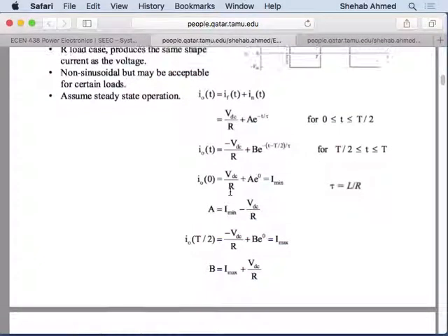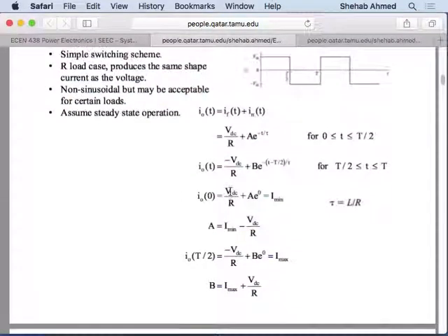From an analysis perspective, what do you think we're going to head after that? If our objective is to look at harmonic content, we're probably not going to use a current equation that's very difficult to come up with a Fourier series for. You have the current waveform, and you can try to find the Fourier series for this current waveform. Or, easier, is the voltage waveform.